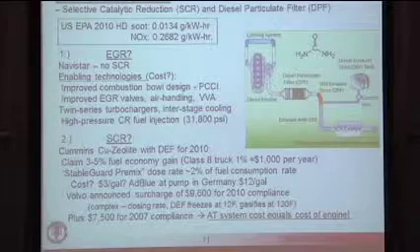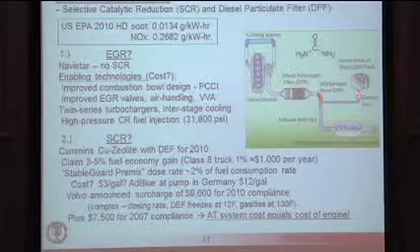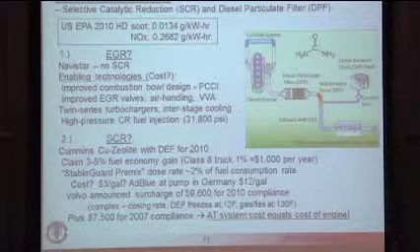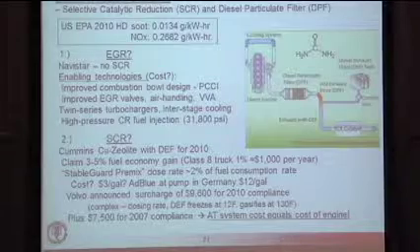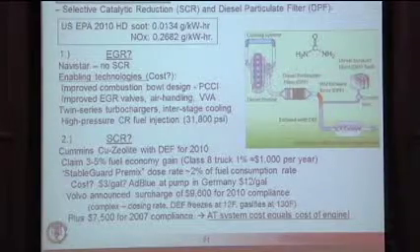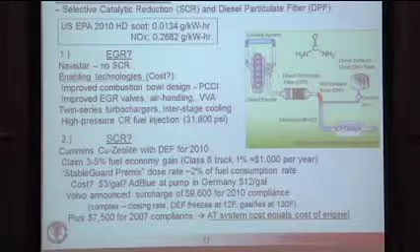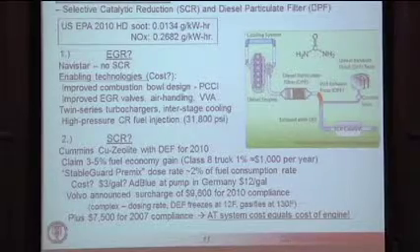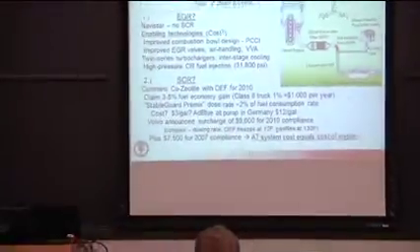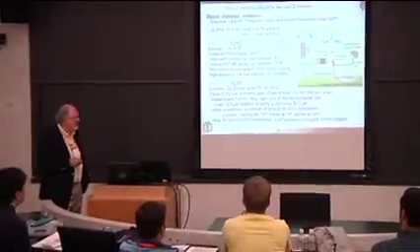The other thing that's kind of interesting, though, is the cost of this system. For example, Volvo published some data that showed that for a truck, it's almost $10,000 to add on this SCR system. That's because you have to change the amount of SCR fluid that's added to the exhaust depending on the engine operating condition, and you have to worry about the fact that this stuff freezes.